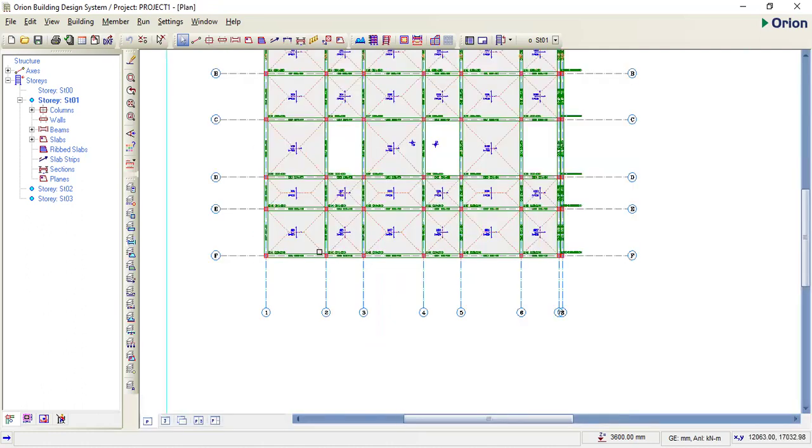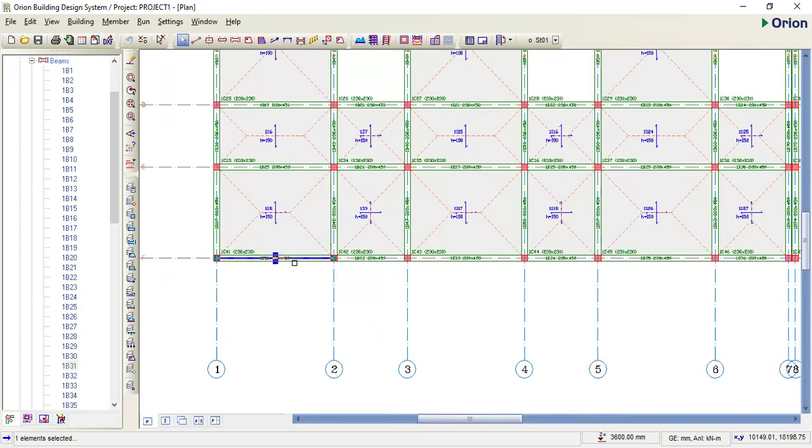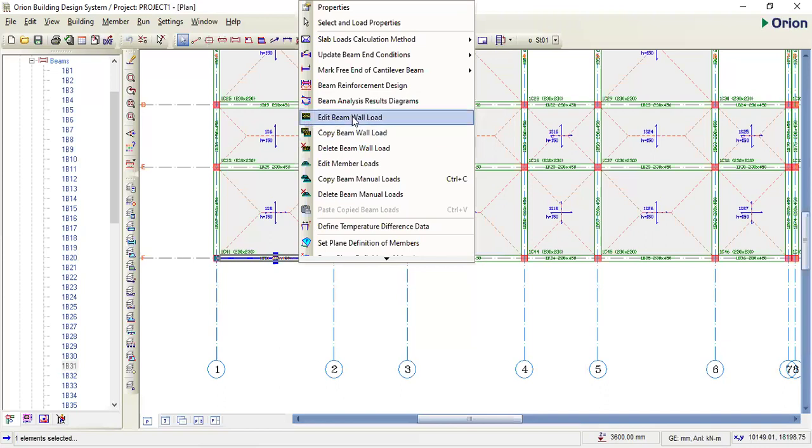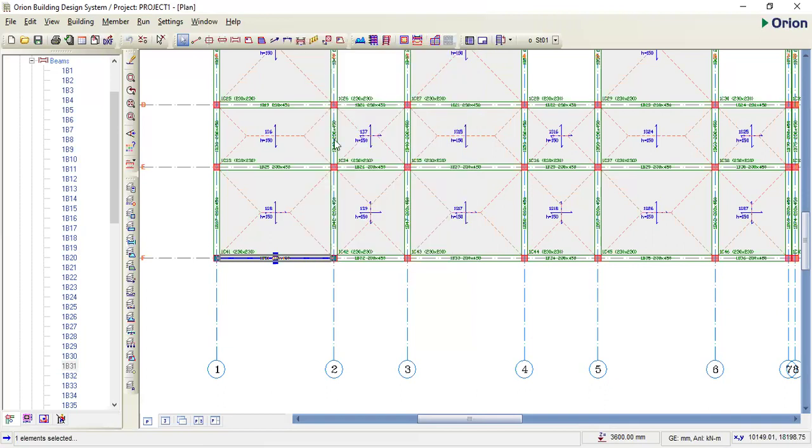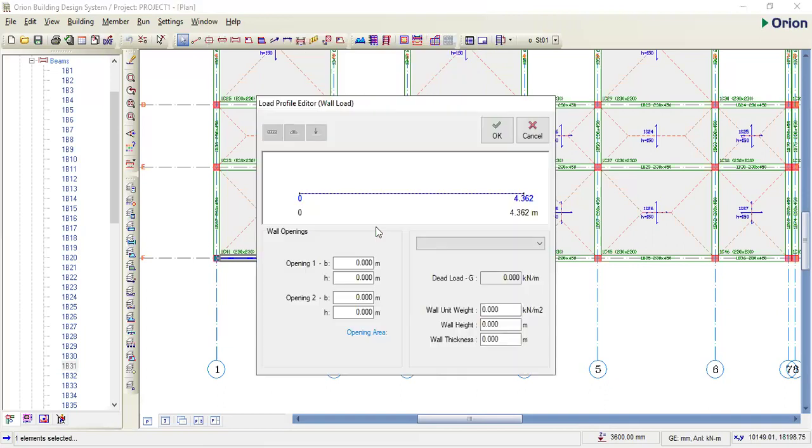All right. In this case, one of the things you should not forget is to load your beams with wall. Because there are blockworks on residential buildings, most of them have walls. So you don't design less than what a beam is carrying on site. So we use external wall. So you load it.